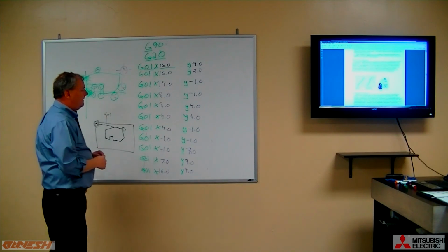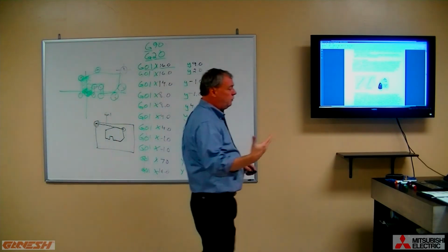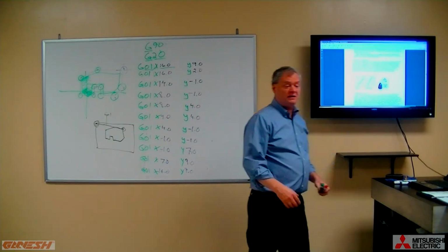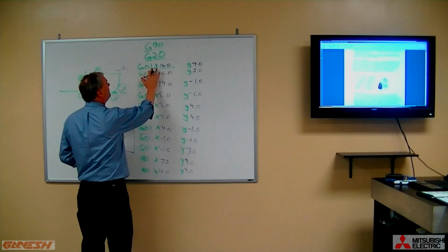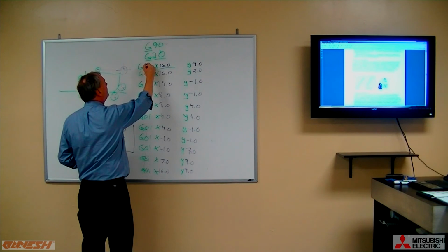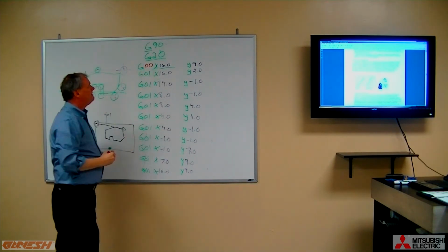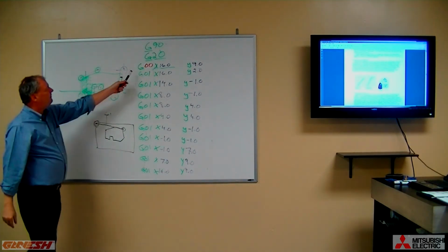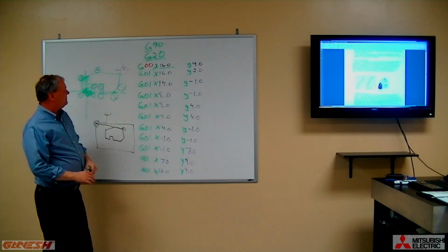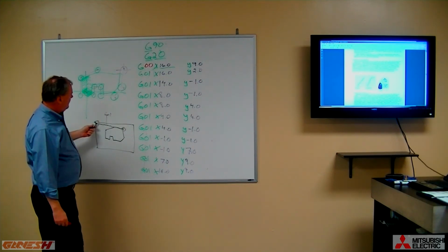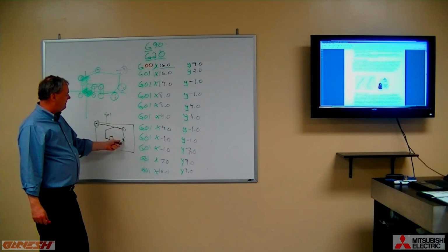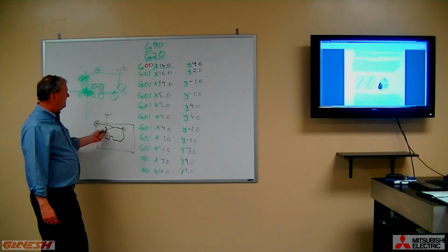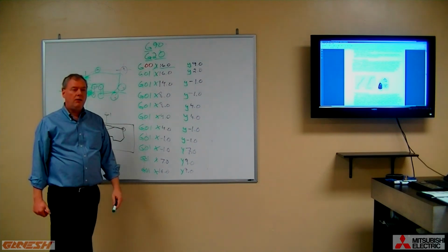So, my question to you was, when is it appropriate to use rapid feed rate? Your answer would be when we're positioning the tool to get it ready for cutting. So by changing this first line to a G00, it's going to say, rapid travel to that position, and then start doing a feed rate around the rest of the profile.